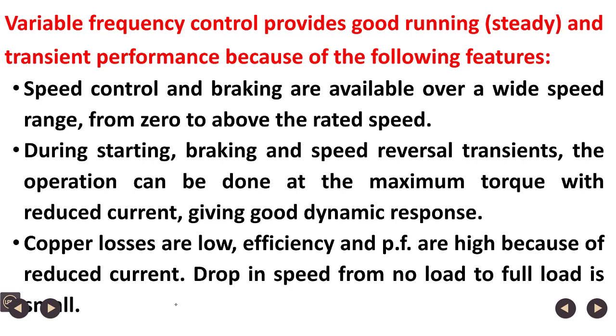So, for the transients of starting, braking and speed reversal, the operation is done at the maximum torque, because torque is maximum. The operation can be done with reduced current. So, transient response is good, because current is less and copper losses are low. So, efficiency is high and power factor is also high because of the reduced current. Drop in speed from no load to full load is also small. So, these are the advantages of variable frequency control.